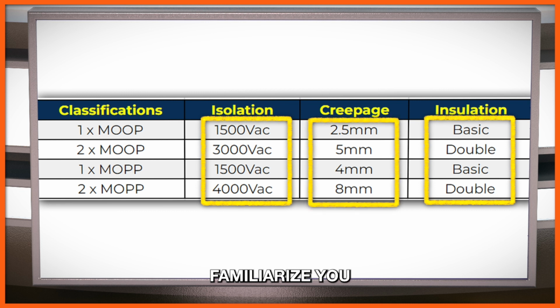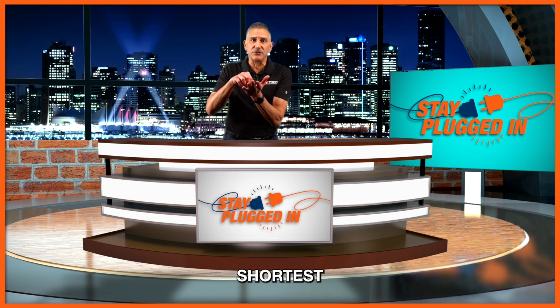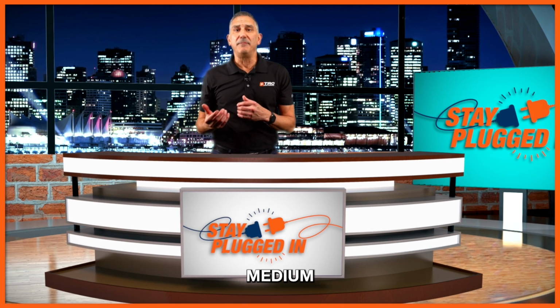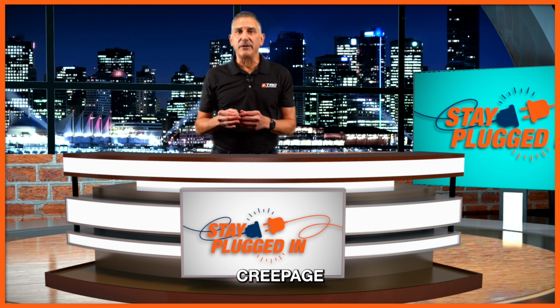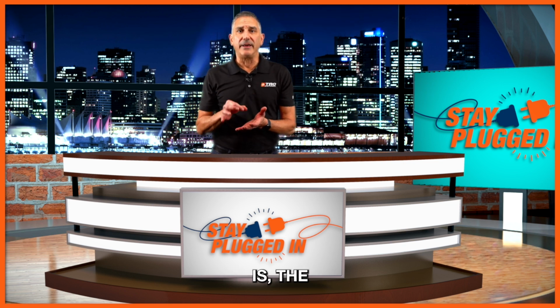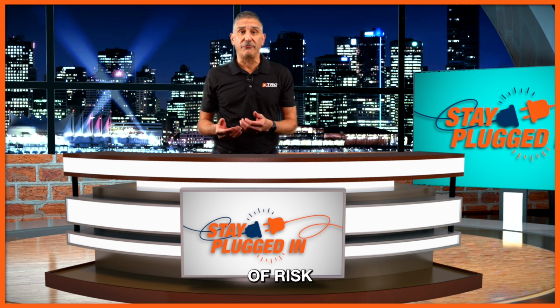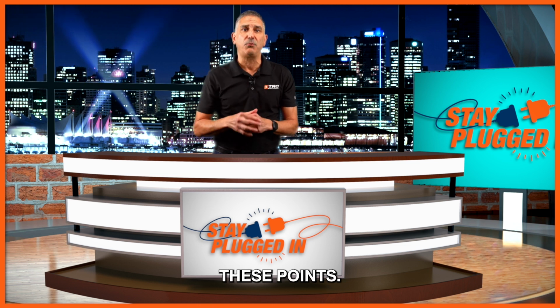And to familiarize you with further creepage, creepage is a measure that's the shortest distance along the surface of an insulation medium between 2 conductive parts. This means that the greater the creepage distance is, the greater the insulation and further reduction of risk of electrical breakdown or arcing between 2 of these points.